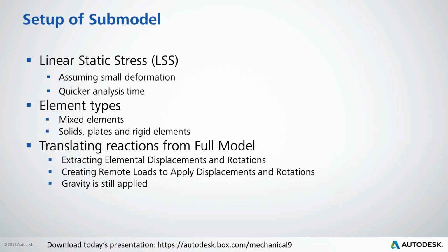And again, our boundary conditions, our loads and conditions, will be displacements and rotations that we extract from the full model. We'll be creating remote loads with the rigid elements to apply these point loads to the more 3D object, and we'll still be applying gravity.